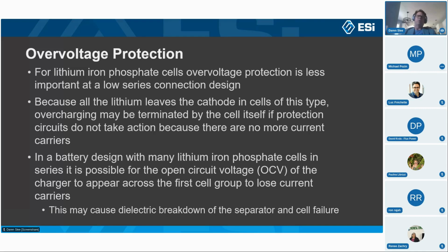When you stack up a lot of lithium iron phosphate batteries into, say, a 100 series battery, well, that's about 30 times a 3 series battery. So you're going to need 30 times that 0.4 volts that I just mentioned. And I'm doing math now, but basically you end up with a much larger headspace on your open circuit voltage.